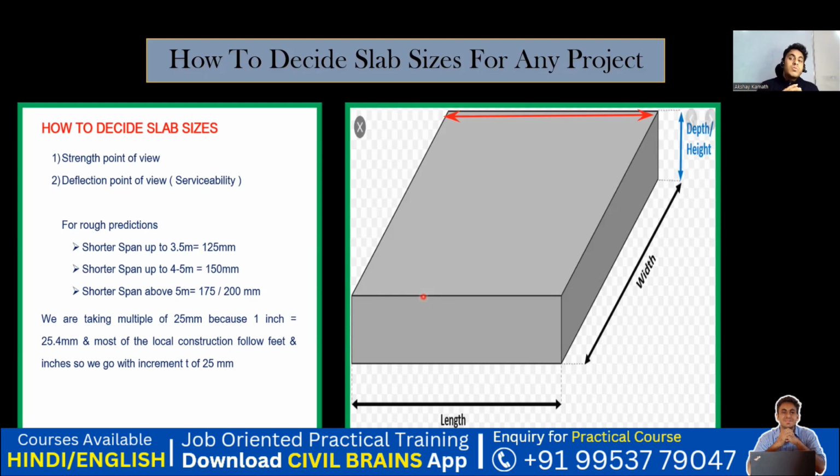So 5 inch comes out to be 125 mm, 6 inch comes out to be 150 mm. And for almost all the construction, 5-inch or a 6-inch is a minimum size of a slab that we go. We don't go with the 7-inch or 8-inch slab unless it's a huge load coming on that. Otherwise, 5-inch and 6-inch is a pretty decent size of a slab that we can use.